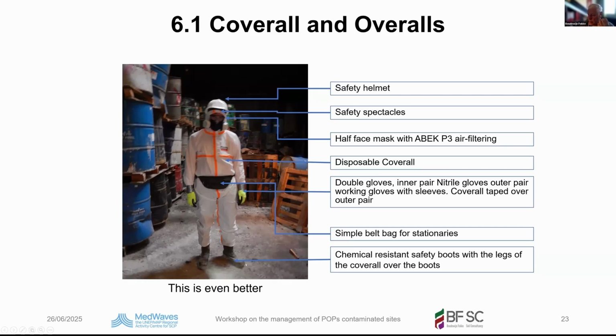And here, the last but not least, chemical resistant safety boots with the legs of the cover overall over the boots. This is very uncomfortable when it's warm, and therefore your working time should be adapted to the situation. And if it's warm, you should allow breaks frequently for drinking, and there should be always a watchman watching people operating under these conditions. And when you see that things go wrong, you can act.